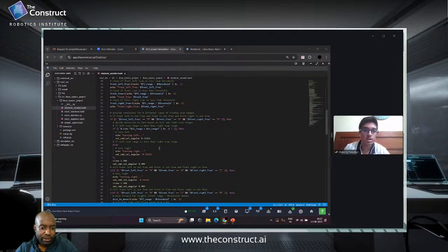I tried putting 0.2 something or 0.1. The bot was turning less, which was preferable, but I decided to keep the same value as the simple patrol.bash, according to how that file is working. According to me, 0.3141 turns a bit more, so I prefer to.